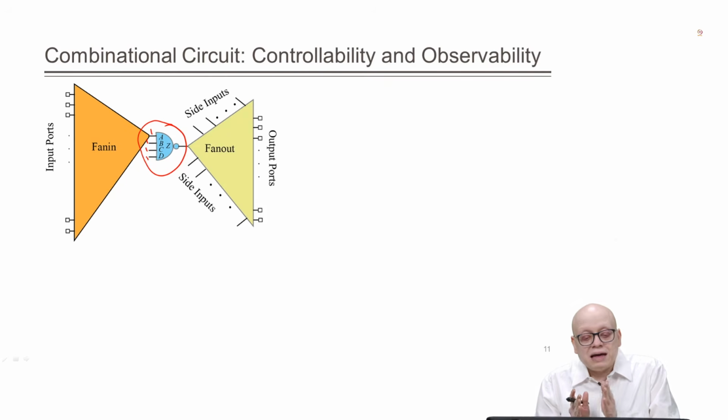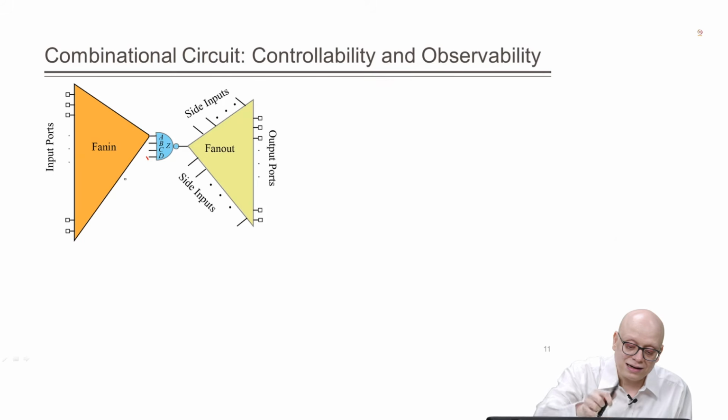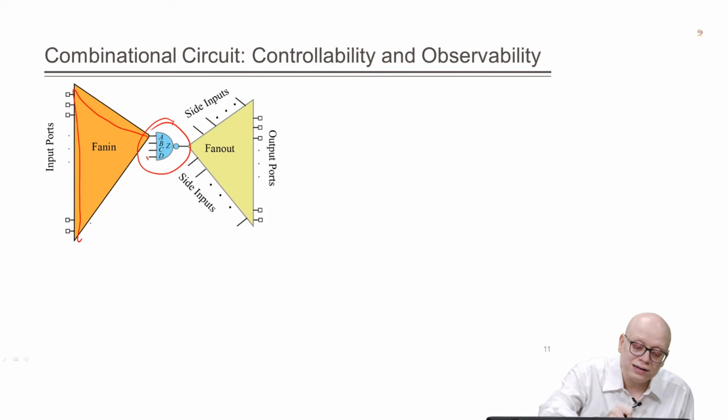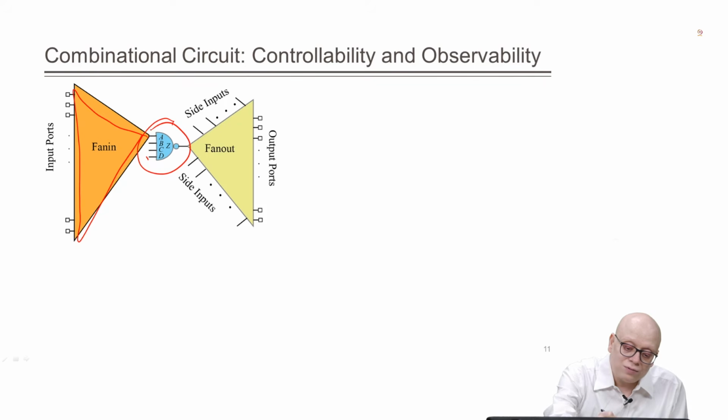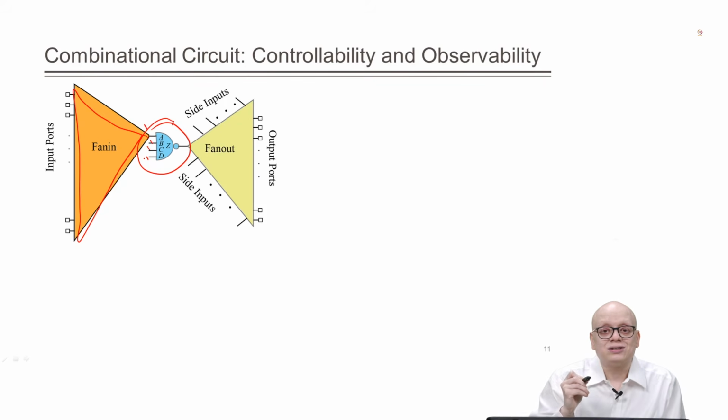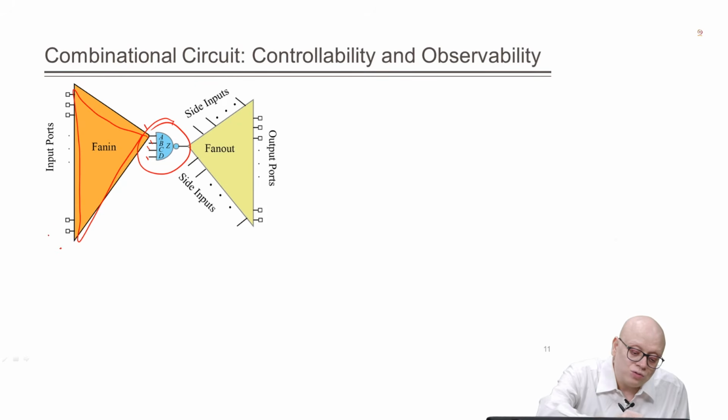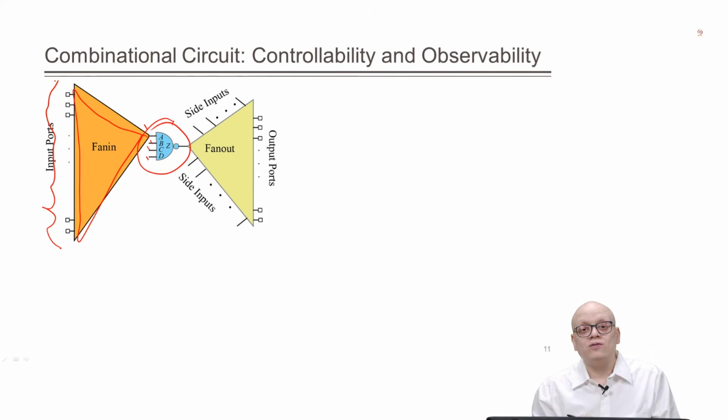But as we move this NAND gate deeper into our logic, for example, here we have shown that this is the NAND gate, and in its fan-in there is a complicated logic structure, a Boolean function which is implemented using logic gates. There can be several levels of logic gates in its fan-in, right. Now, in this case, if we want to apply say 1 1 1 1 test vector at the input pins, we need to find out what would be the right combination of values such that we get the correct value at the input pins of this NAND gate, right.